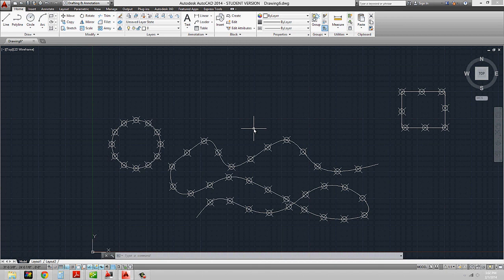It does that for a reason, in order to save a bit of memory. So if you ever find that you drew a circle, and you might draw another circle and it comes out looking segmented too, that's just AutoCAD doing that. A lot of people will spin their wheels trying to create circles and circles. But the real problem is that every time you draw a circle or a curve, it makes it look like these straight lines.